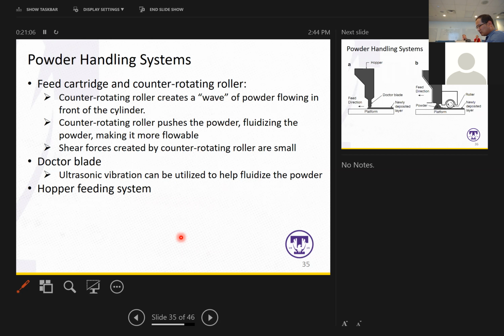Yeah, I think one big concern is that, because of the way additive manufacturing works, it probably has better mechanical or tensile properties in one direction, but not in the other. It's supposed to have weaker tensile properties in the Z direction than in the XY direction. Is it always true? No, it depends on build orientation. Building orientation, right. But if you're building up in Z, that's the weakest direction.